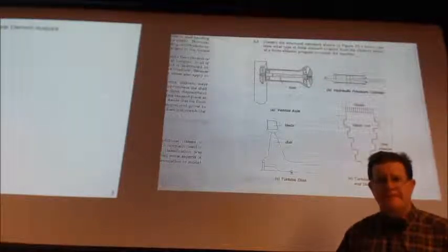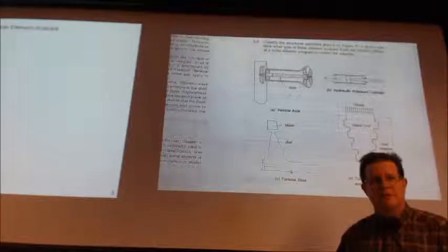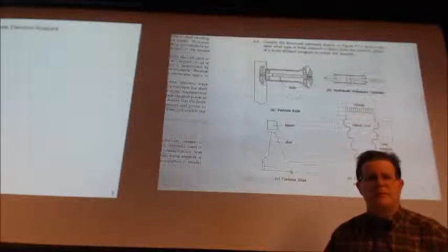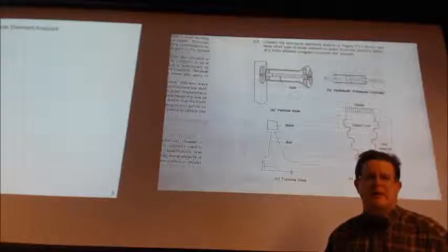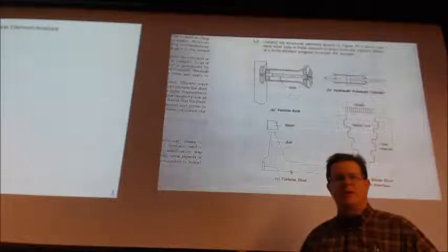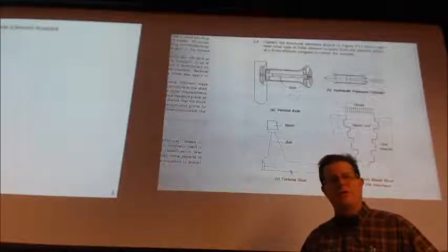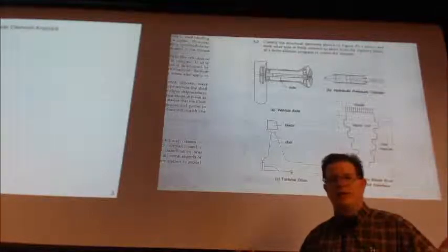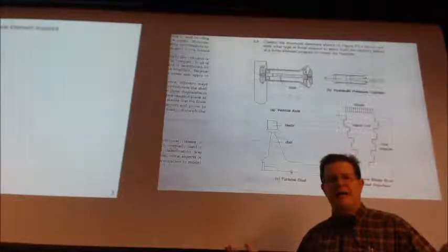It'd have to be a shaft. Well, it doesn't have to be. You can make that like a boom too, can't you? Well, how are the loads on the rod? Well, it's axial loads, right? Typically, they're going to be axial loads. You don't want any bending loads on it. So if they're axial loads, you're going to treat it as a truss. Oh yeah, I guess so. Because it's an axial load, it's only tension or compression. You don't have any bending.